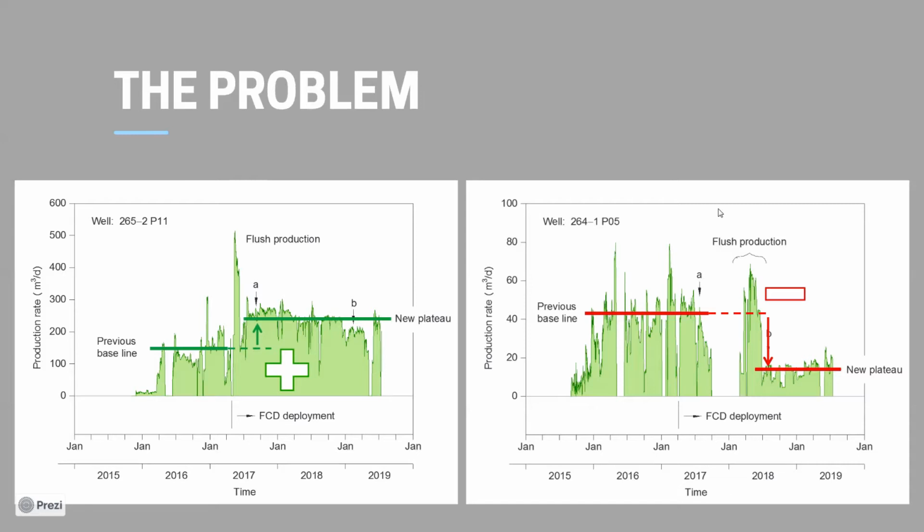Using FCD, we create a very nonlinear system in the wellbore. And the problem is, after drilling, we don't have much time to decide what sort of completion we're going to use, what the restriction is, how the formation is. So we have to make judgments, and normally those judgments are based on experience rather than modeling, because you don't have time.